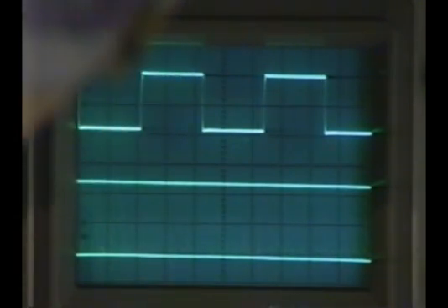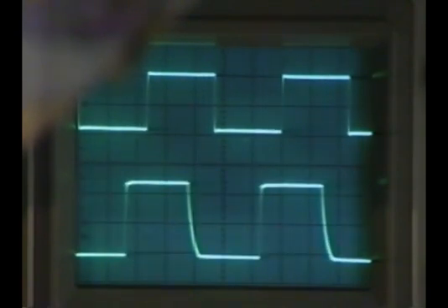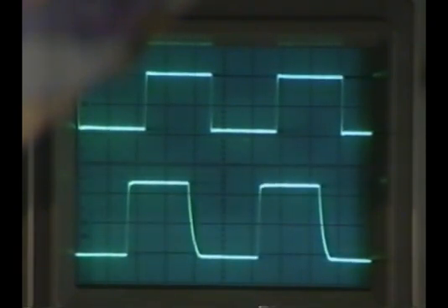Okay, another interesting thing you can see here, there's a lot of lore and so on with PLLs. For example, let me show you something. Here, once I'm locked, I can actually go way, way up here, and then I lose it sort of at the edge. Now what's interesting is if I decrease the frequency, I don't lock immediately again. To actually have it lock, you have to go reasonably far down. Hey, come on. There. And it only locks about there, right?